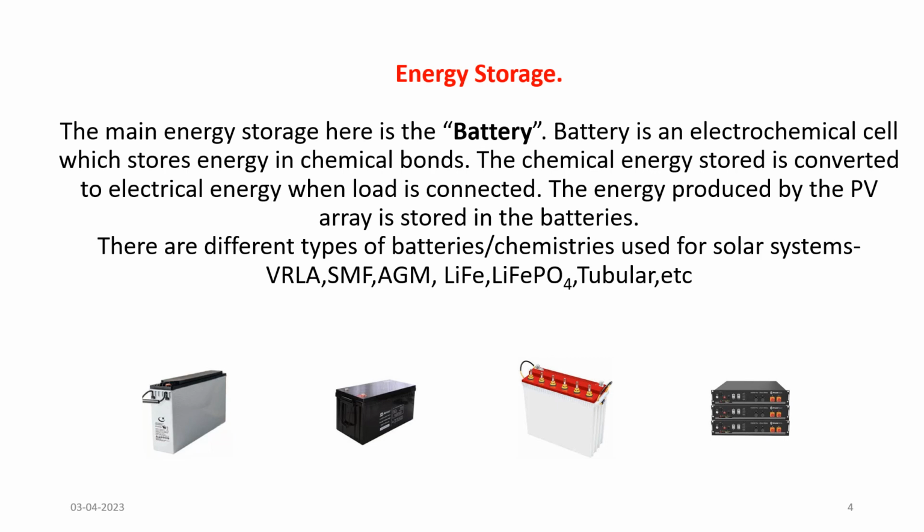All of them are lead acid batteries apart from the lithium ion. The first battery is the front terminal, then some are gel. We have some that we regard as gel battery. We have some that are lead acid battery. The second one is the SMF, that is the sealed maintenance free battery. Don't touch them. Then the tubular, you can see the electrolyte cell indicator, that's the tubular type of battery.